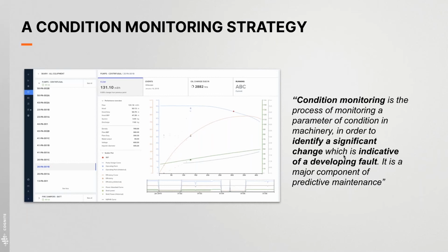In the case where pumps are critical and have a high cost of failure consequence, a vibration monitoring system can be set up, and the results can automatically trigger work orders in the CMMS system using a write-back mechanism. The example emphasizes having a common underlying data foundation with data coming from different source systems contextualized in one layer, with write-backs from applications to the data foundation, so that all the applications can use the enriched data and not end up siloing the enriched outputs.